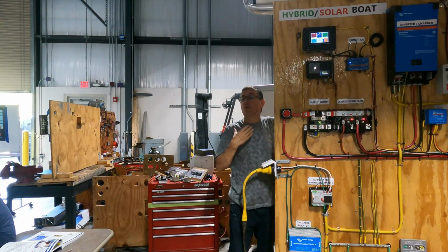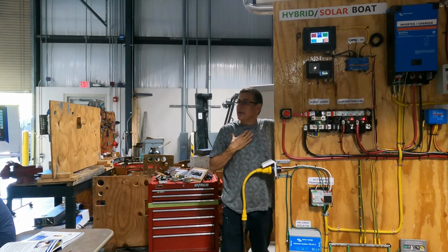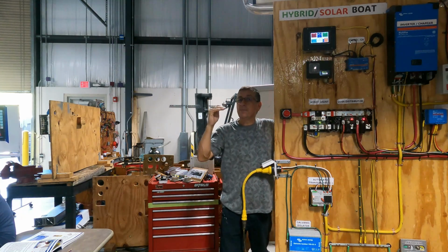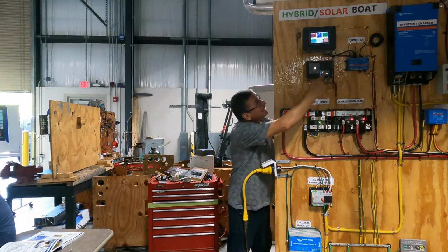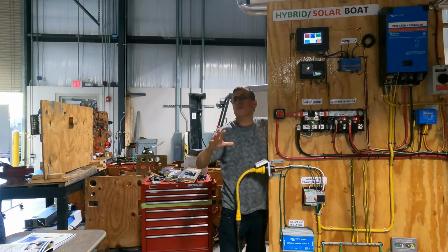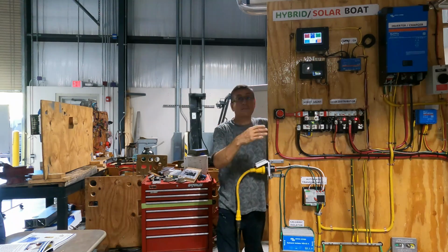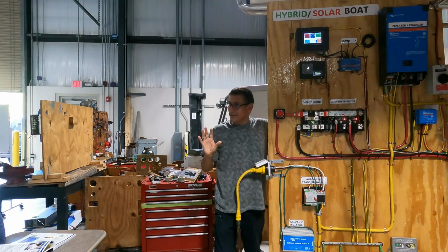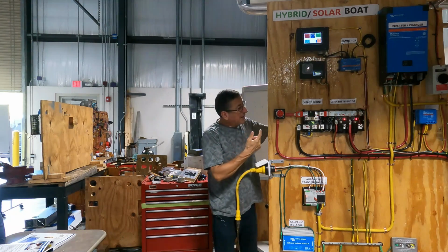Why? Because I wanted that when the level of charge in the battery bank decreases 20%, your generator kicks on. This intelligent computer sends the signal and starts the generator automatically. The generator provides power for the inverter charger and charges the battery bank again. That's the intelligent part. Okay, good.